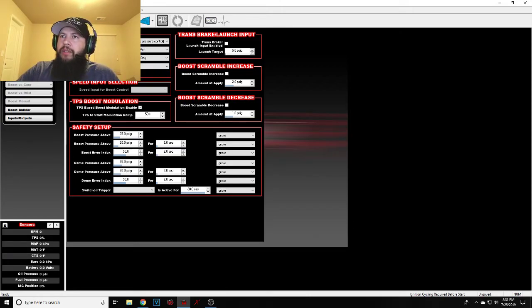I guess the one positive thing is it's an indication of whether you've got an issue or not. So if you are targeting 5, but it's always going higher than that, you may have an exhaust pressure issue or a wastegate priority issue or something like that. If it's spot on, your system's working exactly how it's supposed to be, which is nice.